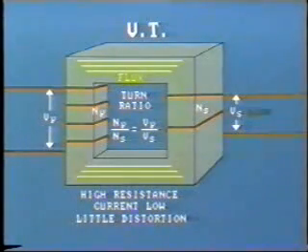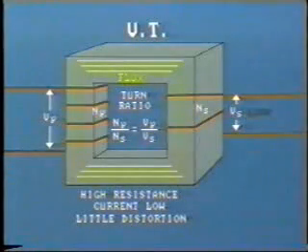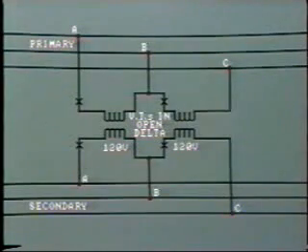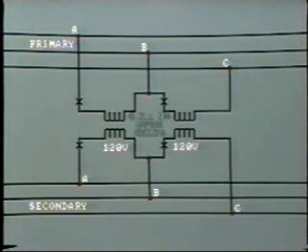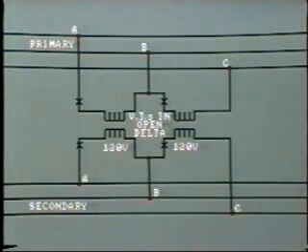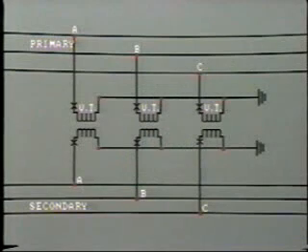The secondary voltage is usually 120 volts. Many protection relays require line-to-line voltage as an input. For this case, 2 VTs are used, connected like this. This actually provides an open delta arrangement on the secondary, and thus we have all 3 line-to-line voltages. Where line-to-neutral voltage is required, such as in generator protection, 3 VTs are normally used, connected like this.